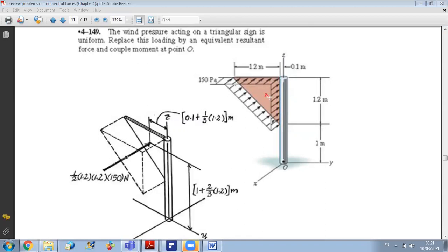It's here. Let's call it G. Okay. Then simply I can just say that the resulting moment is OG because I want the moment about O. So I can just do OG vectorial FR, as simple as that. Okay. So this is why I tell you in 3D sometimes the easiest way is to do the vectorial formulation.